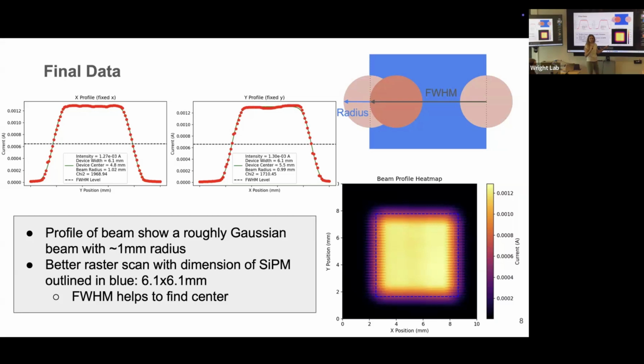So when you do the raster scan, you're trying to shine it on an individual cell? No, it's just to see how the current changes as you get closer, and to show how the dimensions are accurate, but there's no significance to one pixel being fired within the SiPM. So the current you read is not necessarily from a single cell, it can be from a bunch of them.